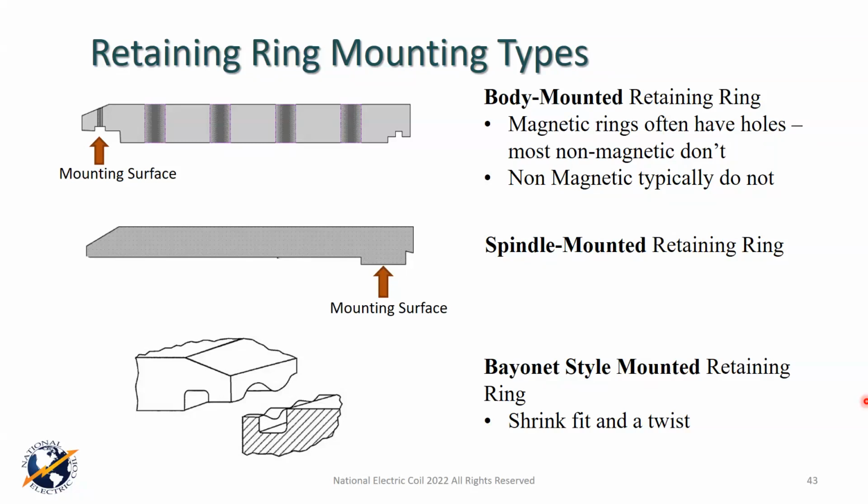And better yet, knowing what all the OEMs say and knowing the potential for stress corrosion cracking, replace them. Plan for it, order them in advance to get a good price, get them prepped and ready to go, and change them out. So that's one of the things I wanted to share with you in regard to that.